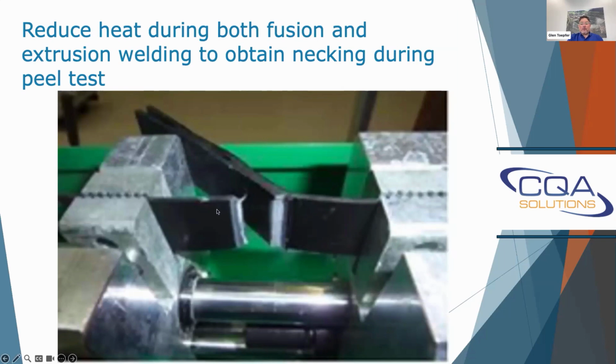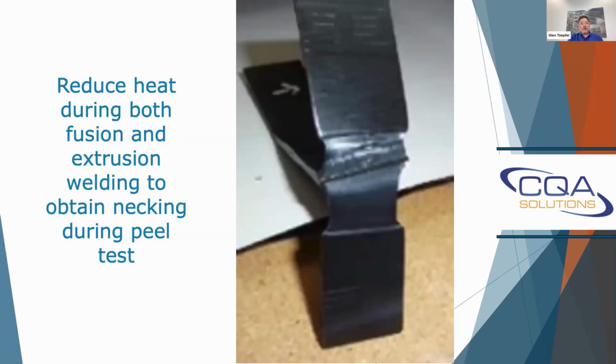It's my belief and the belief of others in this industry that if we cool down the heating a bit, you can return back to the necking that you're seeing on this previous slide without compromising the integrity of the weld and without compromising the integrity of the adjoining geomembrane.